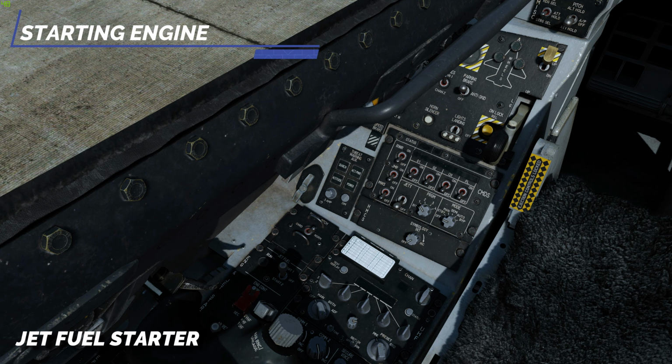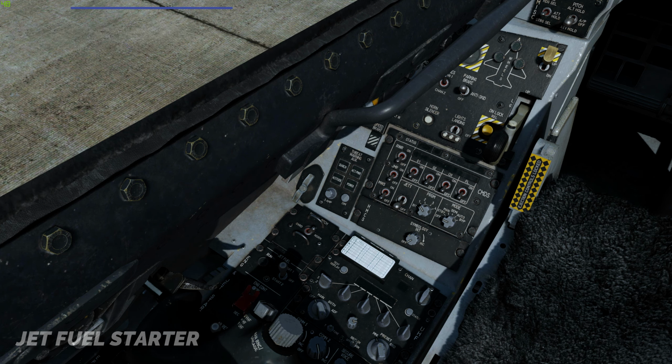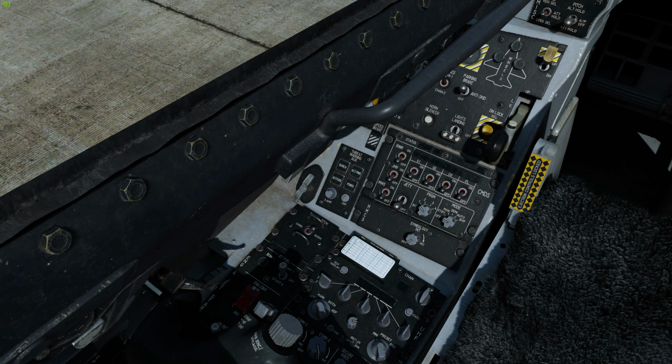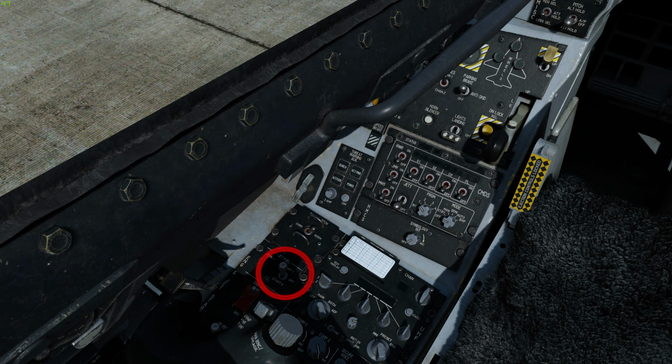The JFS is an independent gas turbine, started by 2 JFS/brake accumulators and charged automatically by hydraulic system B. To vent one or both of the brake/JFS accumulators to the hydraulic start motor, place the JFS switch in the start 1 or start 2 position. The JFS spools up and the engine turbine shaft is driven to 20 to 25% RPM. The JFS run light illuminates.